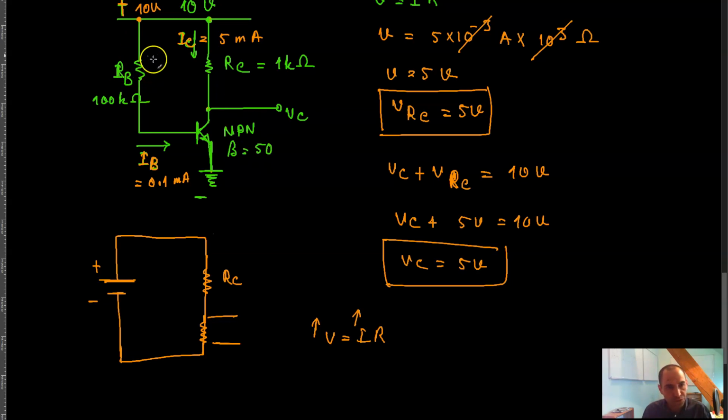So you can put the photocell over here, and depending on how much light the photocell gets, there are different resistances here. Depending on that, you have different currents over here, and depending on that, you have different types of V of C over here, and so on and so forth, right? So that's basically what the transistor does.